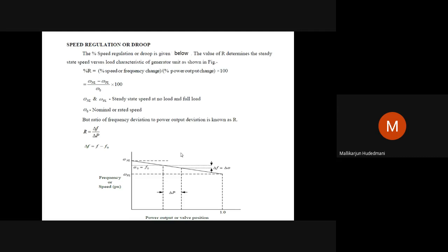What is it that you are going to correct? Input fuel is already sufficient, which is causing a higher frequency or RPM. And how would you address it? That control is not at all good and not at all there. In that regard, a droop characteristic is a favorable control for generator governors.